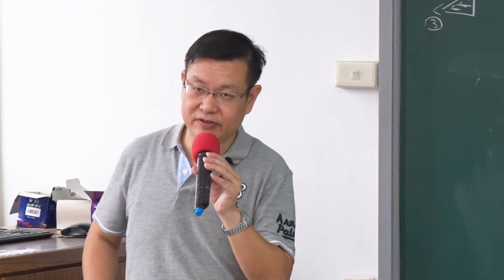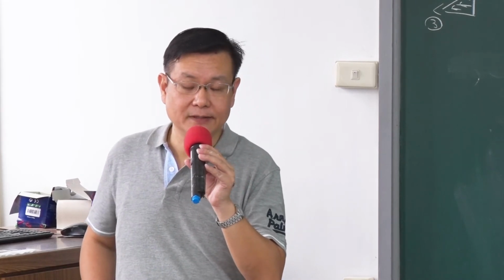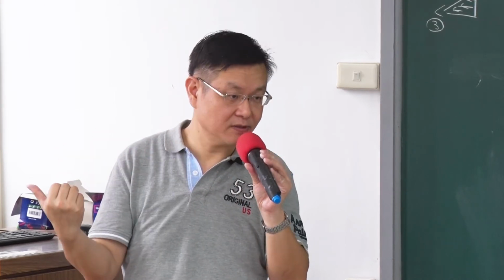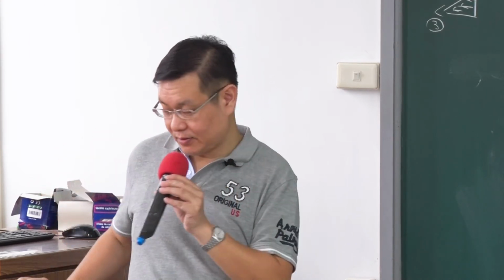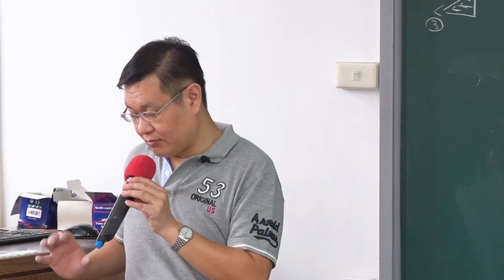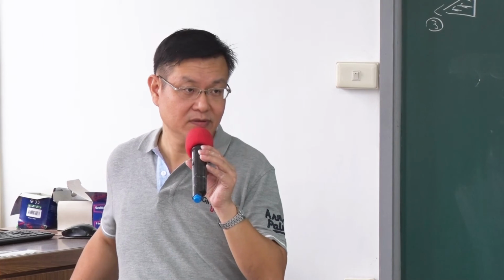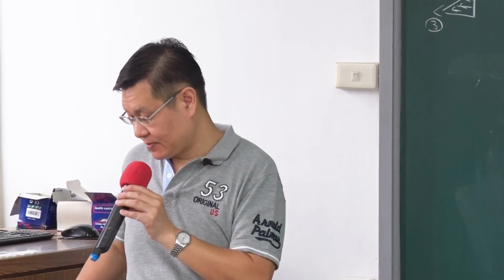So that's why in the past, when we were talking about bulk machining, we talked about a special method. We call it etch stop, right? By using the etch stop technique, you can preserve some structure of single crystalline silicon as a sensor, because the single crystalline silicon substrate can give you a very high gauge factor. It becomes a very good sensor.